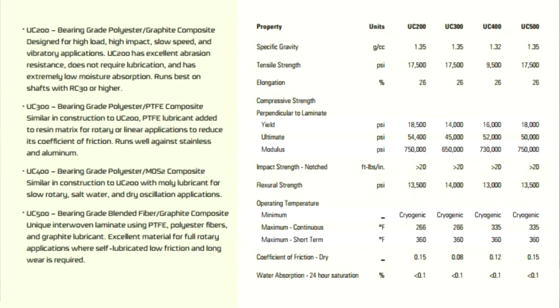When you see a compressive strength number, whether it's a composite or any plastic, that is generally going to be its compressive strength at its extreme condition. That's the point at which it basically will self-destruct. You don't want to design a bearing around its self-destruct point. So the compressive strength data, whether it's on the UltraComp or the CJ or any other material, is really telling you this is the point at which that material is going to explode.